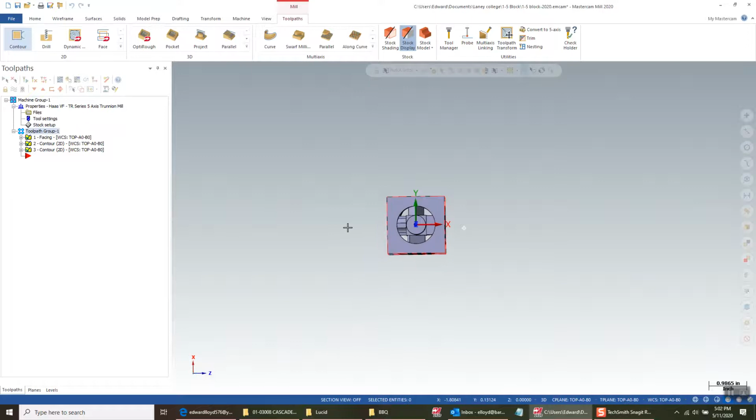And you think it's going to rotate to either show you this face or show you that face, right, through the spindle. Thing is, if it rotates this way, then the body of that 5th axis unit is going to be facing you, the operator.